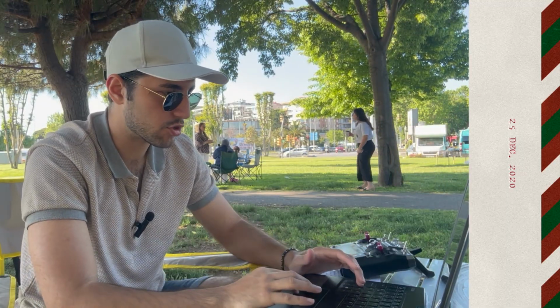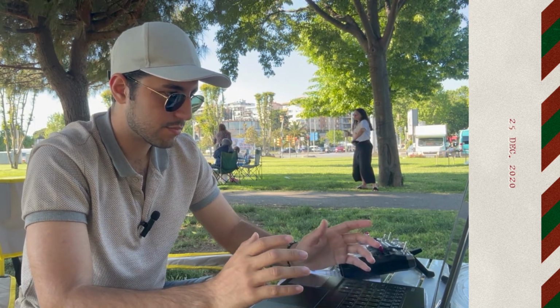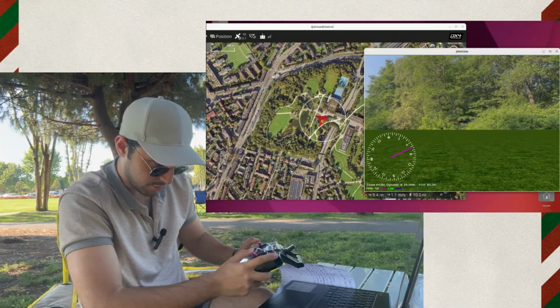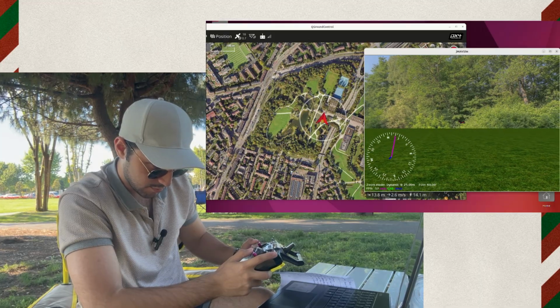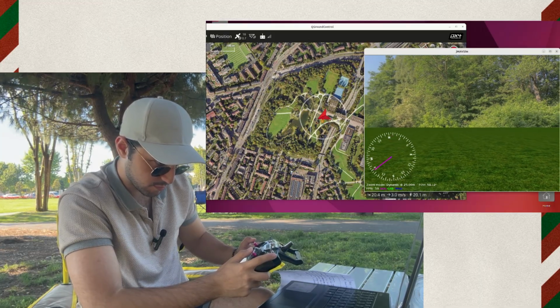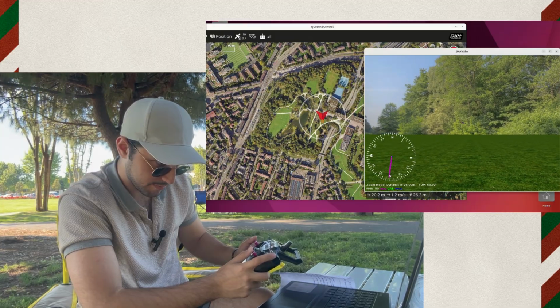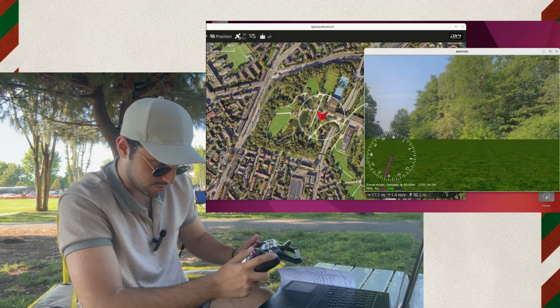Now this time I have changed the setup to HITL simulation. The process is exactly the same as what I showed you in the video. What you need to remember is that software in hardware acts as a telemetry monitor, but in HITL, QGC actively serves as a communication gateway between the flight controller and an external 3D simulator. Okay, this time also I'm driving it. I've changed to position flight mode. I'm going to the top, going to the right.